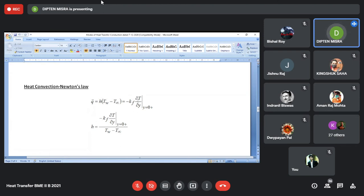So if we can evaluate this temperature gradient in the y direction at y equal to 0 plus, then multiply it with the conductivity of the fluid with a minus sign, you get the heat flux. So you could find the heat flux through this. Now, the question is how do you know this temperature gradient? That is again something that is not known a priori. It is the job of the heat transfer people, the people involved in research, to find the value of h under different situations.